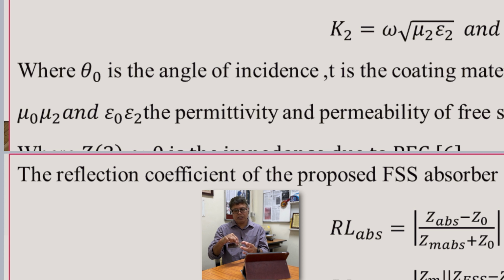Further, if we place diodes in between the gaps, these three gaps are there, so we can place Schottky diodes in these gaps, and then these diodes will accumulate the charge carriers, and then we can connect these diodes to a rectifier circuit using a doubler or quadruple configuration, and we can connect a load. So this is the AC voltage available across the diodes. With the help of a rectifier, either a doubler circuit or a voltage multiplier, quadruple circuit, we will be able to convert this AC voltage into DC voltage, and the DC voltage will be sufficient to cater to IoT devices. So this way the ambient energy can be converted into a corresponding low DC voltage.